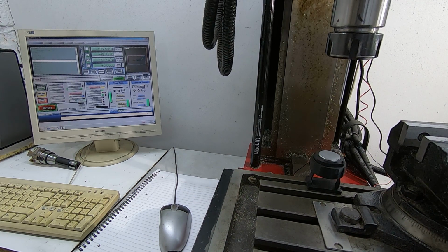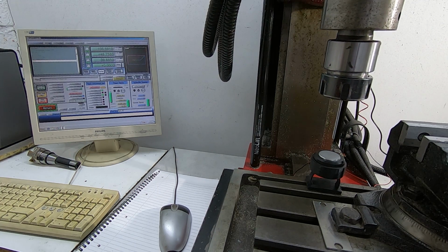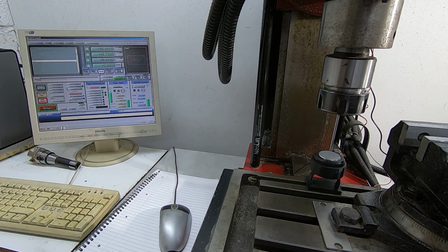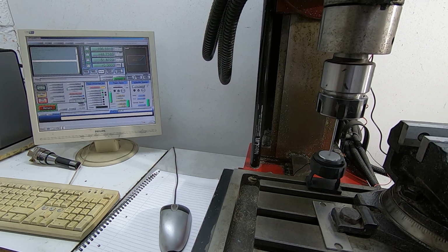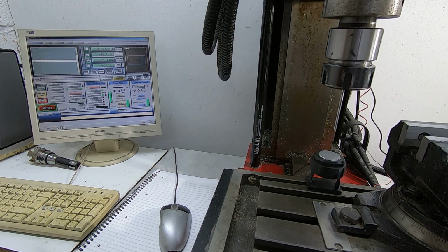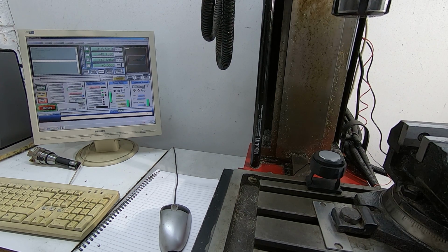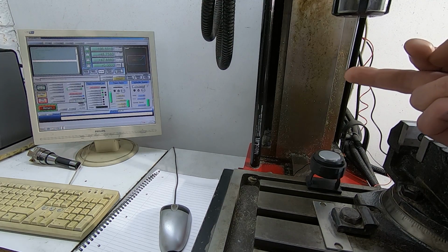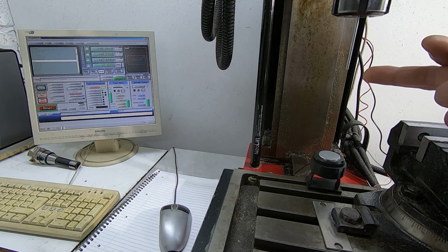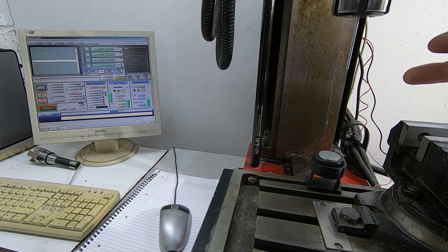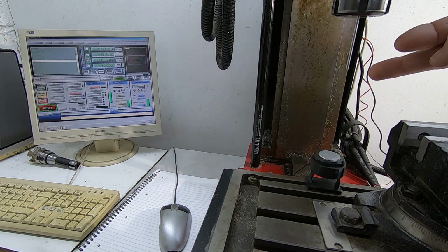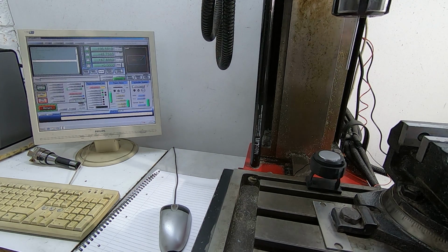We'll then move to the plate, go down to the start position, and then it will probe down until it just touches that plate, and then it goes up to allow us to physically change the tool. Okay, so it's now zeroed. It's zeroed this tip in the G54 fixture offsets, and what we're going to do now is change the length of the tool just to simulate a tool change.